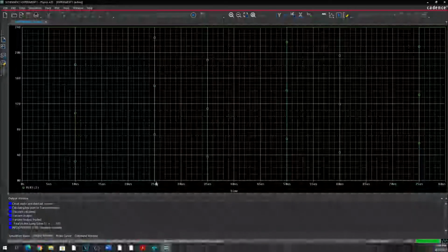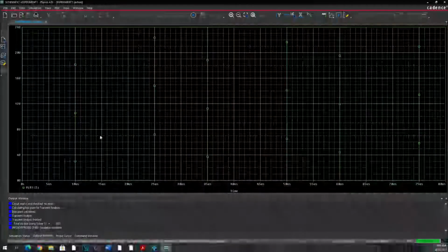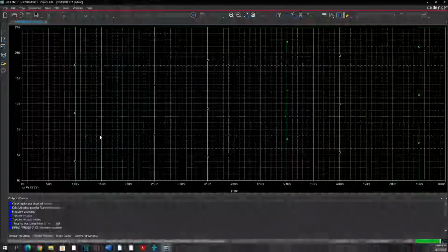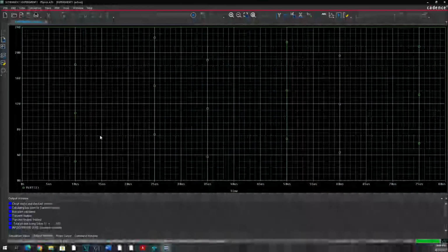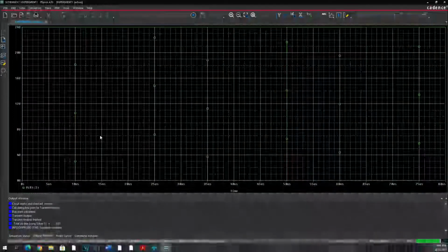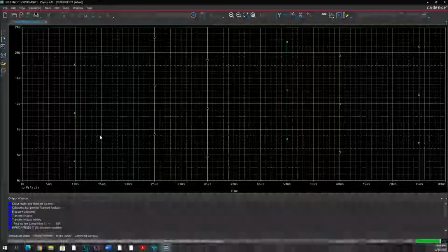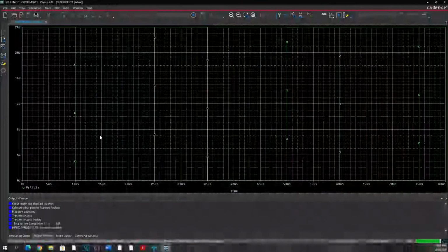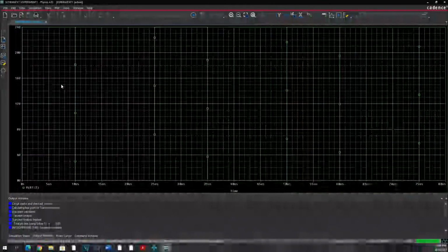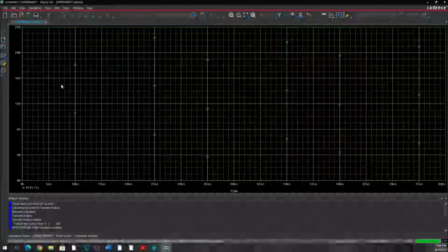Then it rises again after 25 microseconds. In comparison with the switch control voltage, the waveform that we see here in our load resistor voltage is in phase with the switch control voltage. It is because it has an identical rise time and fall time as the switch control voltage waveform. The only difference between each other is the peak voltage of the pulses.